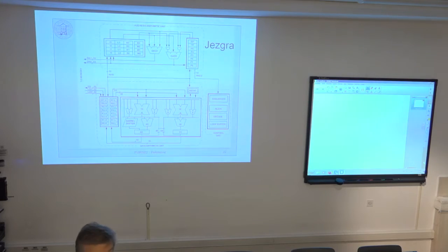So the same set of arguments, for example x and y, are first added here and subtracted here. And that is useful again exactly for implementation of the butterfly in fast Fourier transform implementation, because for one branch you have to add two arguments, for another branch you have to subtract two arguments. And if you can do this in a single instruction, it is the best way. I have two arguments, here they are added together, here they are subtracted, one from the other. Okay? But I cannot have multiplication in one and addition in another one.